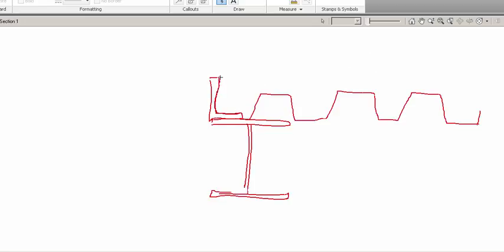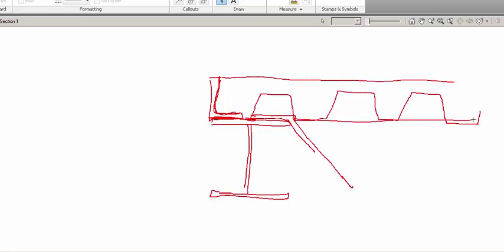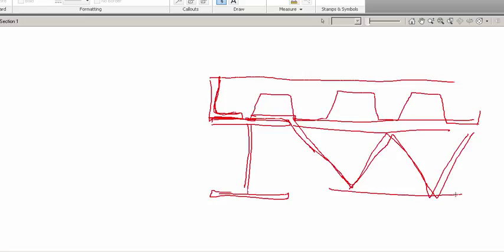Now what the angle does is it actually stops the concrete and creates a boundary for everything, so they can weld right here, and then they can weld the decking itself to the joist below and wherever else it is, pour the concrete in, and that's how you get your typical floor system. Another trick is they may lay an open web steel joist right here and set it on the big steel girder beam, and then here it goes out this way, and this is your open web steel joist, which is holding up the metal deck, which is holding up the concrete, which is holding up us on the floor, with the angle kind of binding it all together. So that's one of the tricks that we'll use with angles.